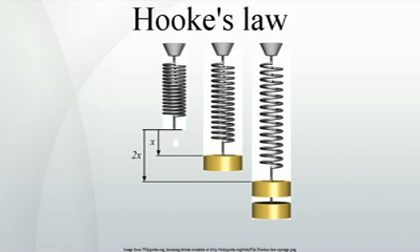Linear elasticity theory for continuous media. Isotropic materials. See viscosity for an analogous development for viscous fluids. Isotropic materials are characterized by properties which are independent of direction in space. Physical equations involving isotropic materials must therefore be independent of the coordinate system chosen to represent them. The strain tensor is a symmetric tensor.